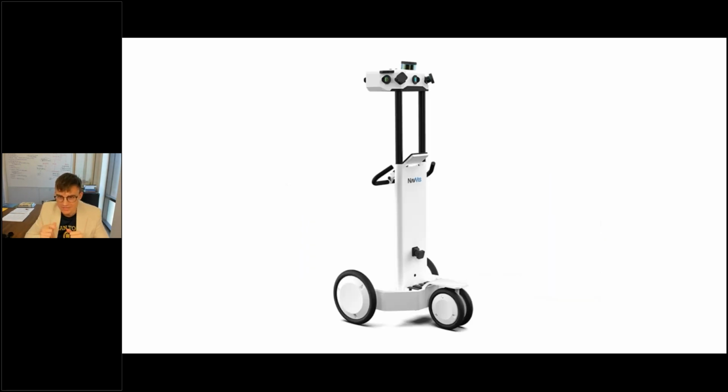Cart systems achieve accuracy somewhere in between tripod mounted and handheld. The wheels of the cart provide an added signal to correct for drift errors during SLAM. But in exchange for the additional accuracy, you lose mobility. It's more difficult to get upstairs, more difficult to get through cluttered areas.